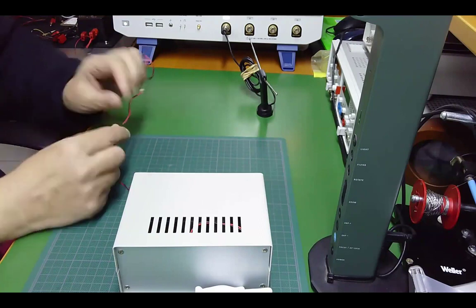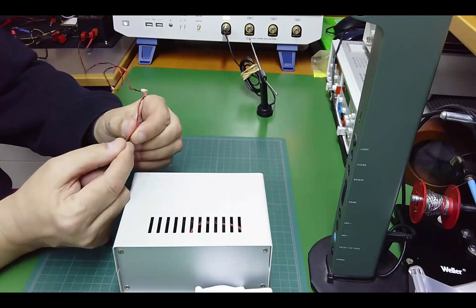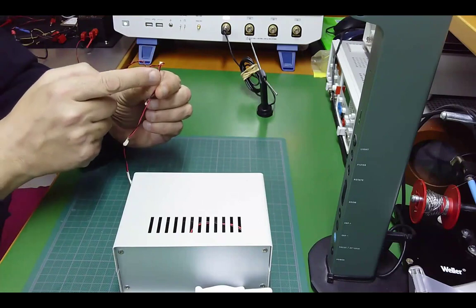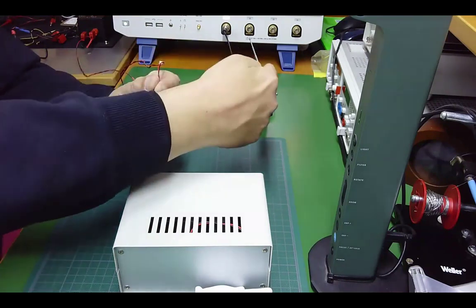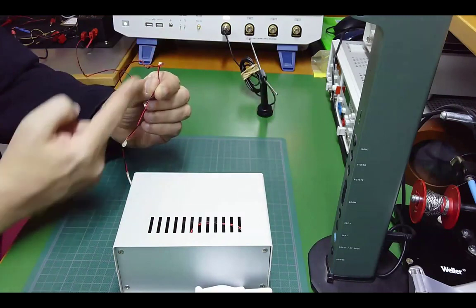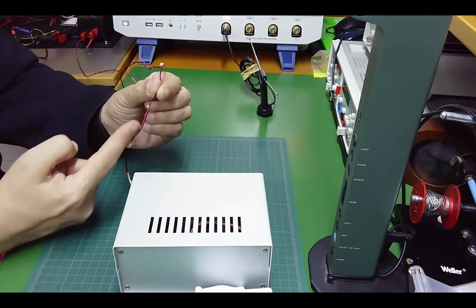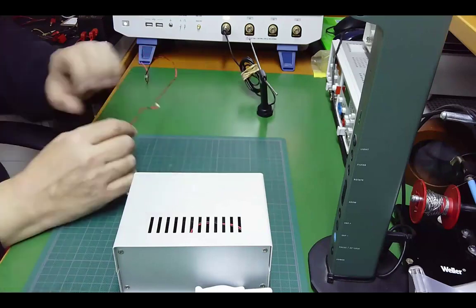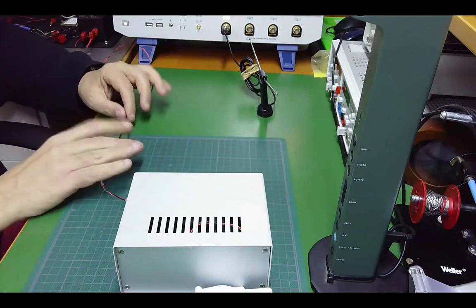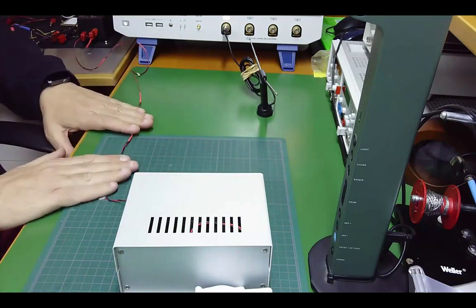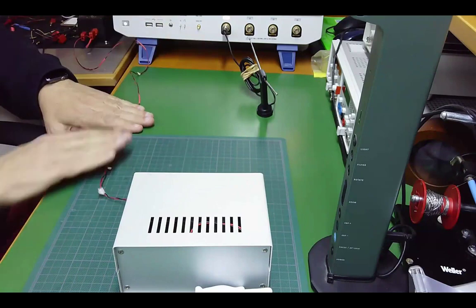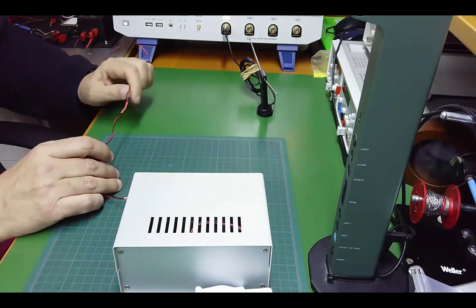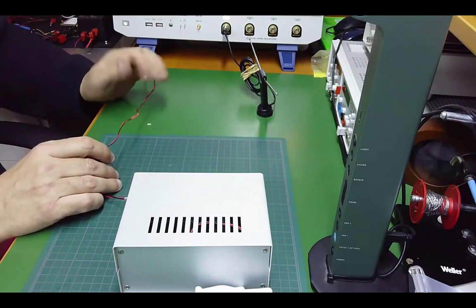Why? Because usually you put the red and the black wire close to each other. So the current going through the red wire and creating a magnetic field is canceled by the current going in the black wire in the opposite direction, creating an opposite magnetic field. So in theory, the magnetic and electric fields created by this cable are canceled at some distance. This is what we call the cancellation effect, and this is what we try to do when designing a circuit, to avoid loops.